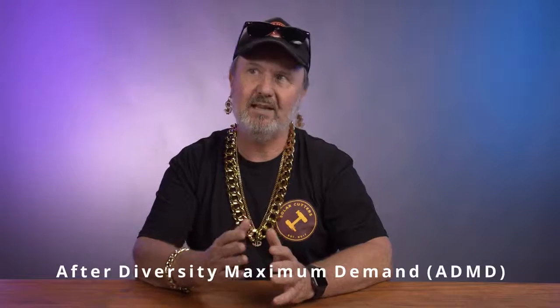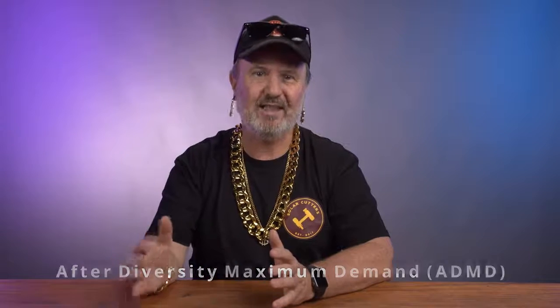Really, I'm going to focus on what's known as maximum demand calculations. Now, maximum demand calculations are something that you might be familiar with for on-grid installations, where you've got a certain capacity from the grid. You have to consider the number of socket outlets and light fittings and dedicated appliances, etc., and work out what the maximum demand after diversity, MDAD, is. Now, diversity is your friend when you're on grid because basically the grid is an infinite source of energy, well, just about. You're only limited by the capacity of your supply.